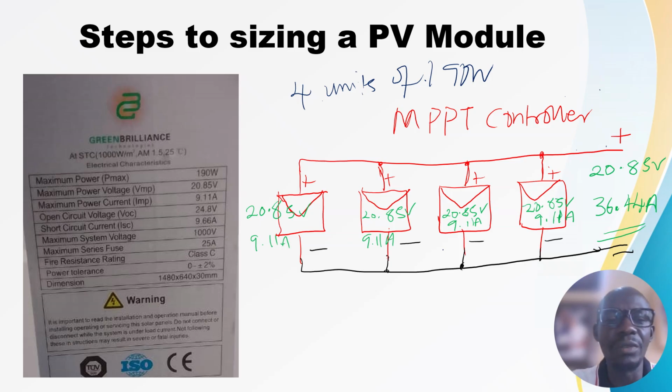And for that battery, let me shift this in before I end this slide. It is accepted that you must add at least 10% of the amperage of the battery to charge your system. I have a 12-volt 220Ah battery.